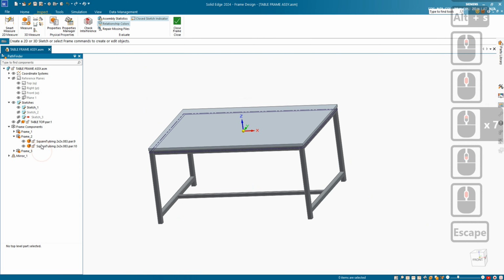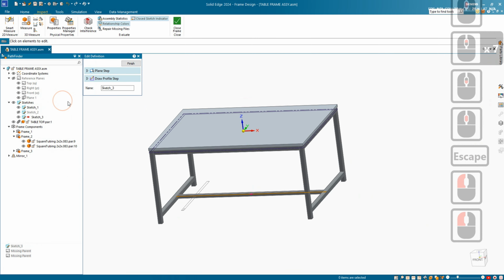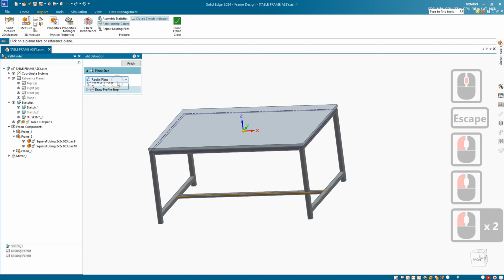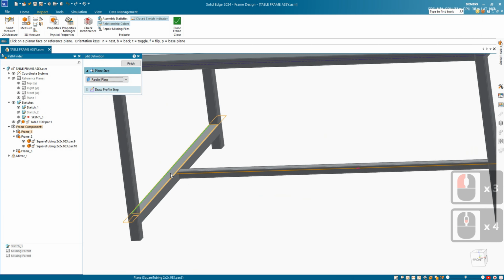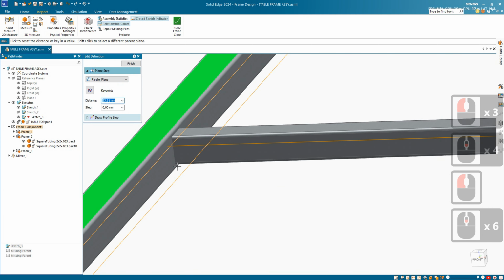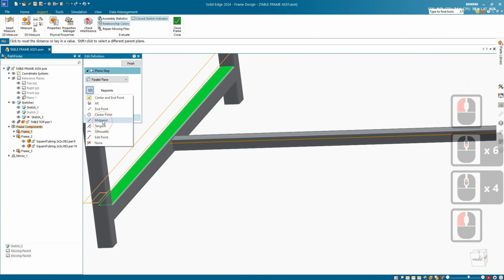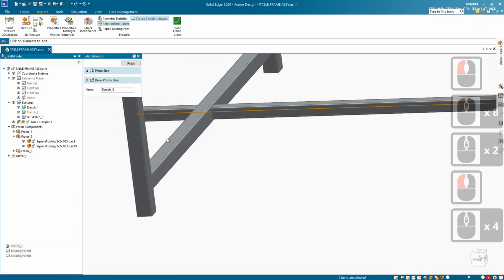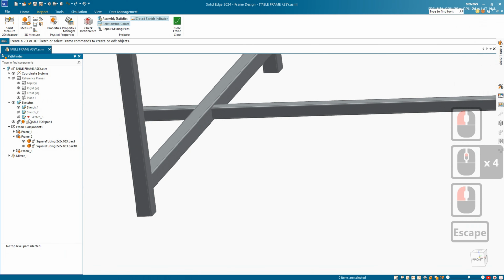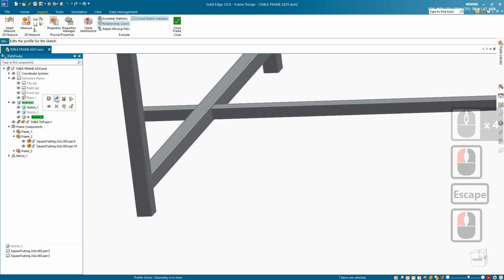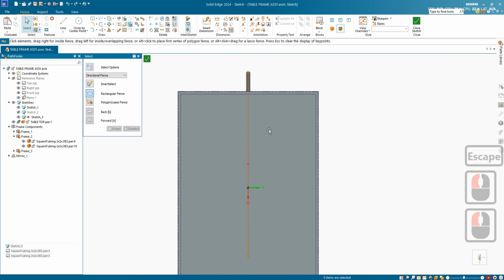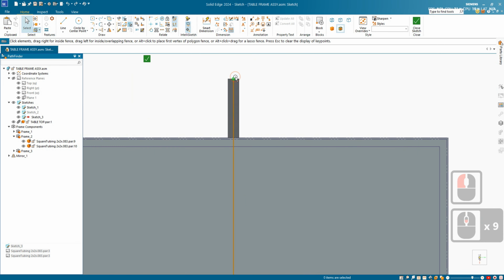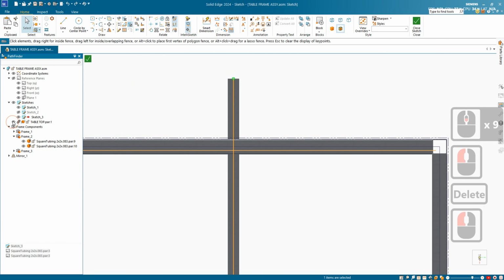Next, you'll see that sketch 3 also lost some of its reference geometry, in which case we need to reselect the plane. So we just go select the parallel plane from that face to the midpoint over there. And then you need to redefine where that line is. So you can see it's showing orange, so it's lost its reference geometry.